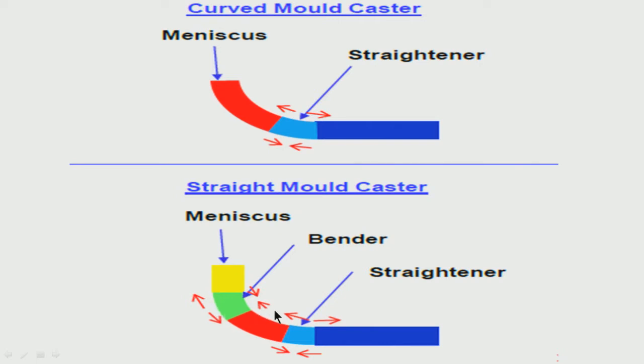So, the stresses on the shell will be something at certain locations, and at the opposite outer radius it may be something else. It may be tensile here, compressive here, and compressive here, tensile there. These aspects I will discuss later on when we come to the continuous cast quality, whether there will be cracks and all, but right now try to understand what is happening.